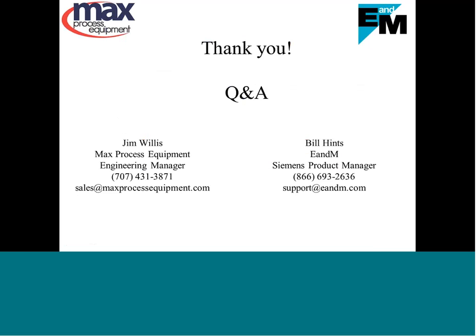First one is, how many PID loops can a processor run? The number you can run is really determined by the time base that we're using for PID. In other words, we have to execute all of these PID loops within an interrupt time. So if we've got a 100 millisecond interrupt, we have to execute everything in that 100 milliseconds, or else we actually run over ourselves.